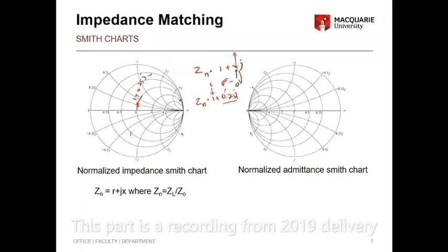Okay, so same way you'll have here 1 plus 0.5j, here it will be 1 plus j. Likewise you can represent any impedance which has a real part and an imaginary part on this circle, right? So I was talking about, all the time I was talking about 1, which is 50 ohms. Now assume,